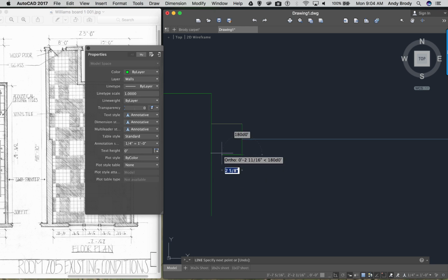However, I want to show you there is something called a temporary O-snap that will allow me to make sure my line is perpendicular. And the way you access that, normally we've been seeing these little green icons. This one says endpoint, this one says midpoint, this one says endpoint. Those are called O-snaps, object snaps, and those force the cursor to snap to particular geometric points on a line or other object. And normally there are several of these turned on.